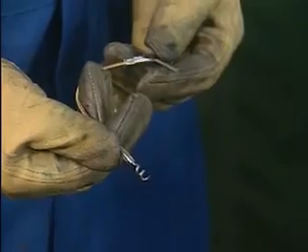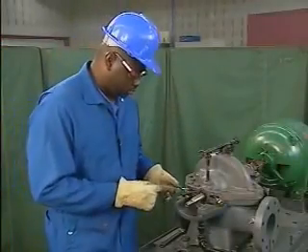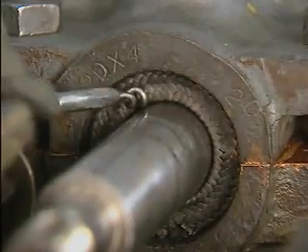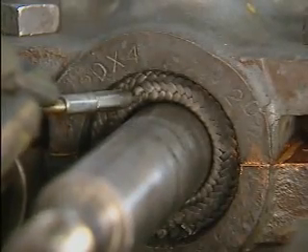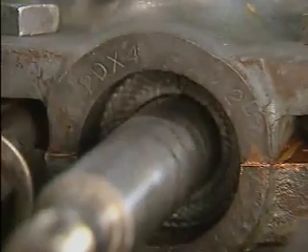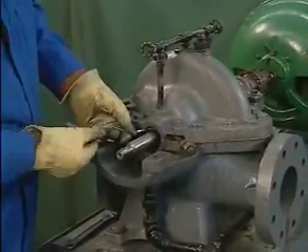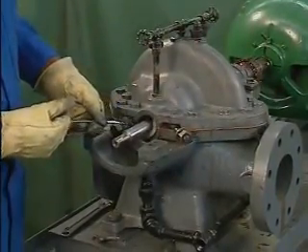It consists of a corkscrew tip, a flexible shaft, and a handle. The mechanic presses the tip of the packing puller against the first ring of packing and turns it until it's firmly embedded in the packing. He then pulls the packing ring out of the stuffing box. The mechanic removes the next packing ring in the same way. He screws in the puller and pulls out the ring of packing.